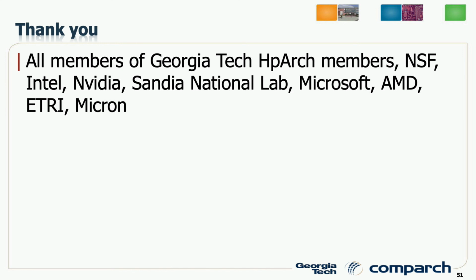Thanks for the talk. I'm curious about how to handle the long latency while accessing the DRAM directly without cache for the PIM. In other words, how to handle the data hazard given the DRAM access latency in the pipeline. We cannot really reduce the DIMM latency. So what we could do is move the computation close to the DRAM. That will reduce the DRAM latencies. Compute on DIMM is one of the examples for that.